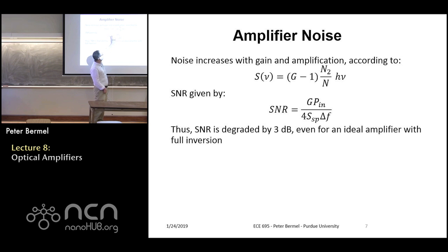So in net, it's not necessarily a bad thing, but you have this G-1 factor. So then that means that the net gain from G over G-1 is not great at really high Gs. And you also have this degradation of delta F, basically the frequency bandwidth. So even in the most ideal case, you usually get a slight degradation in the signal to noise ratio.